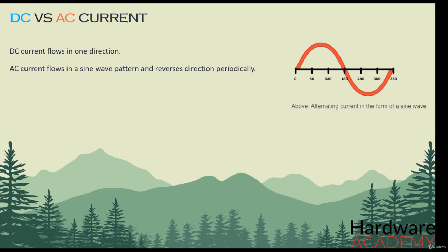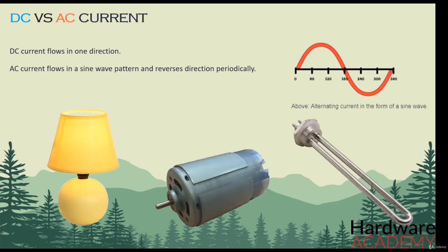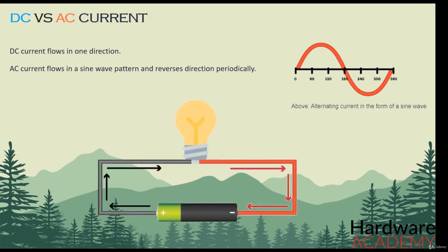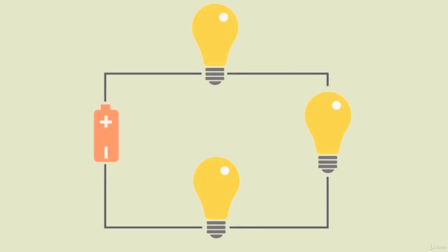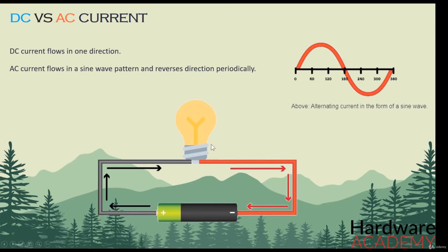You might already know this and it's kinda evident, but any component like lamp, motor, heating element that converts electrical energy into some other form of energy like light, rotation, motion, heat uses current. As we said in the previous course, this light bulb in engineering terms is called a load. When additional loads are added to a circuit, the circuit must deliver more current. And the size of conductors, fuses, and the components themselves will determine how much current will flow through the circuit.